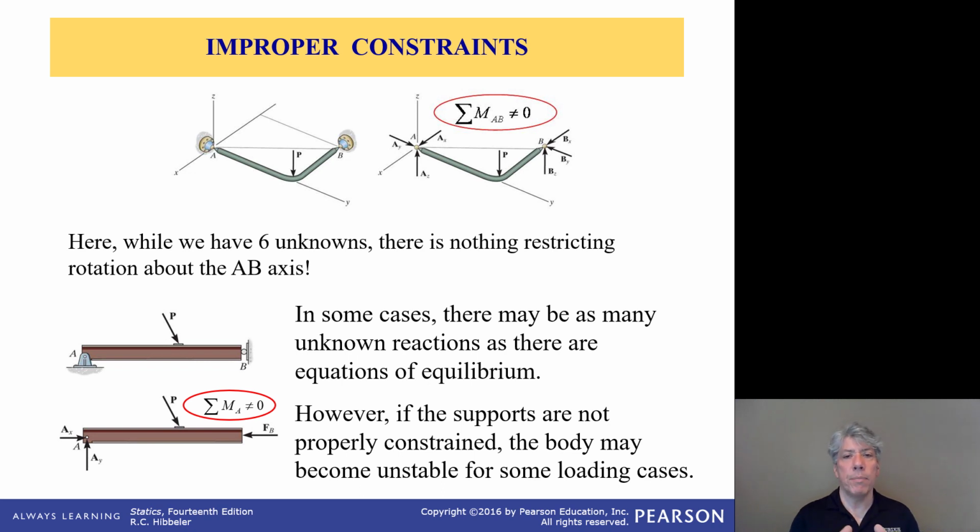But what I did is I put out at the four corners, I attached rods, and then I put those rods to either side of the tree. And in thinking about it, I realized it could be unstable because since the rods are below, it's possible the whole deck could just pivot about this line that I had made, much like the first example in this slide. And so what I decided to do was to run a horizontal support that was tied to the tree that supported the center of the tree house and prevented the tree house from pivoting about its supports at the bottom.